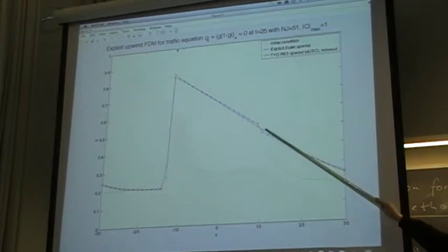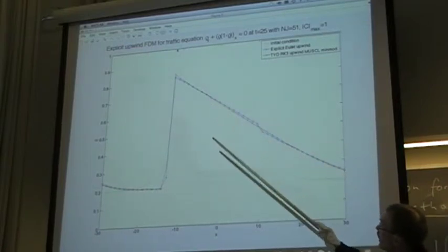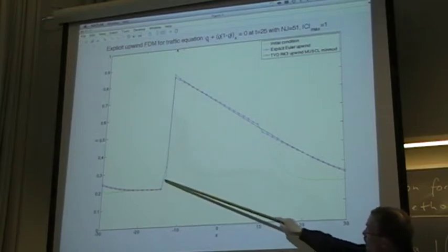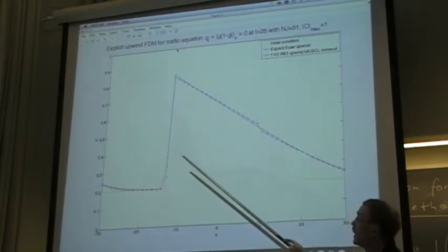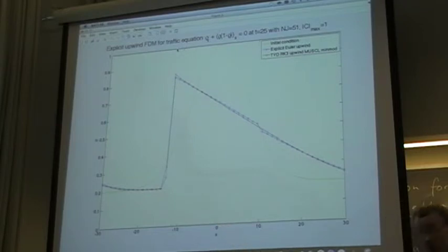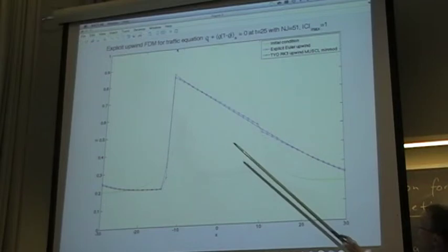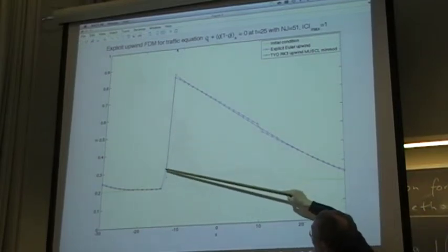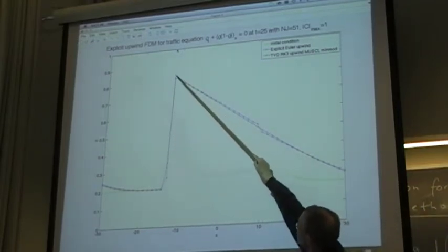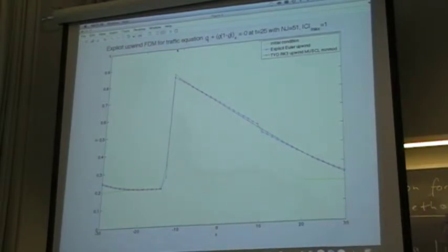So we see it is going quite smoothly, and also the shock is resolved similarly well as with the upwind method, which does a good job here, because we chose the C max as 1. So we have essentially only 1 point in the shock. Here's a little kink there with the MUSCL scheme, but not so serious. So in general, we get an improvement. We get more accurate results.